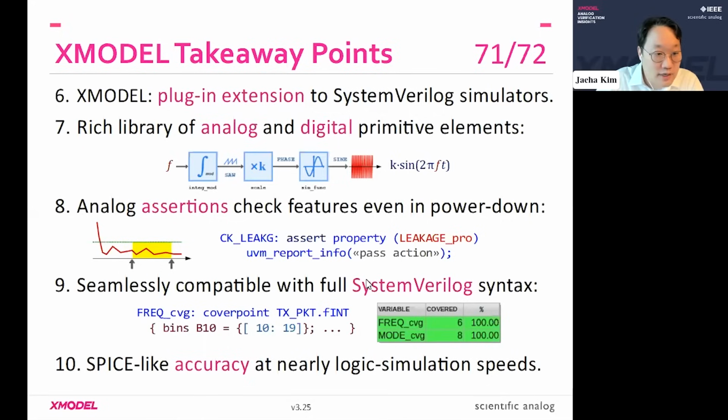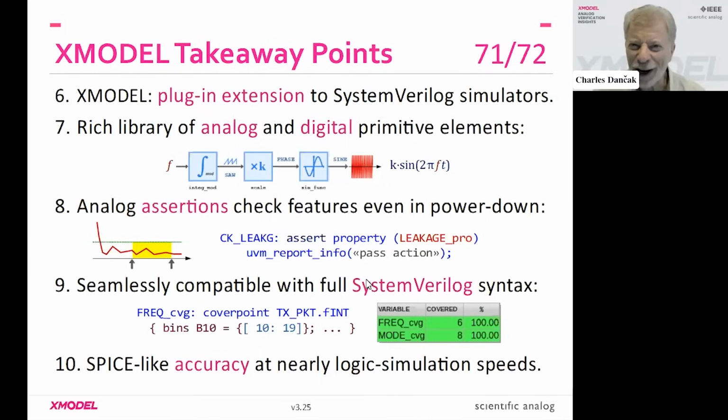Okay, so here's the second question from Lucas. Any specific reason for monitoring the inputs on the driver and not on a specific input monitor? If you wanted to reuse the agent without sending any stimuli as a passive agent, we would miss the inputs, right? Yeah, great question, and you're absolutely right. If there are any dropped packets, you could be feeding information to the scoreboard that was never actually launched.